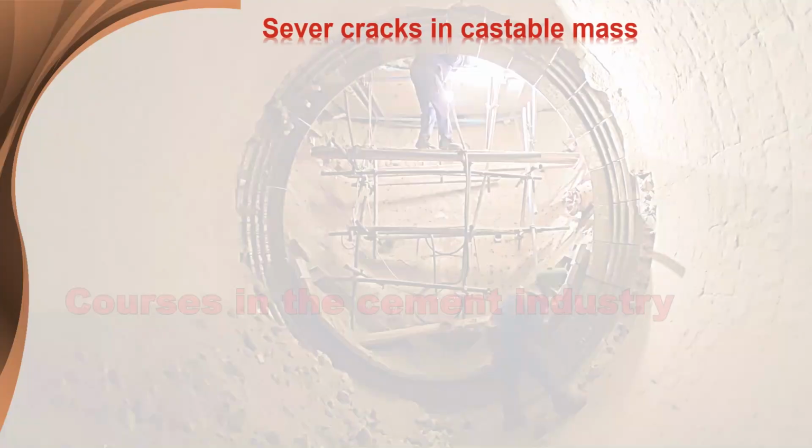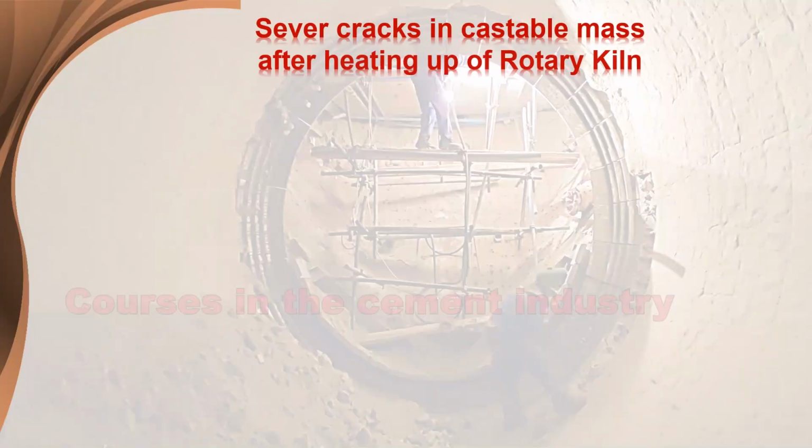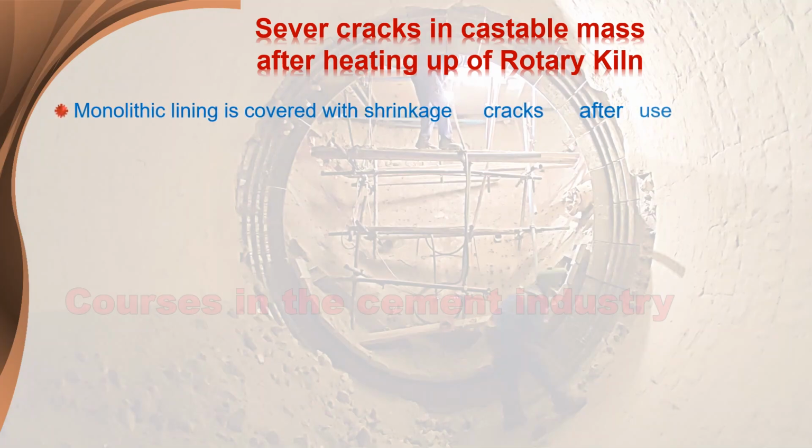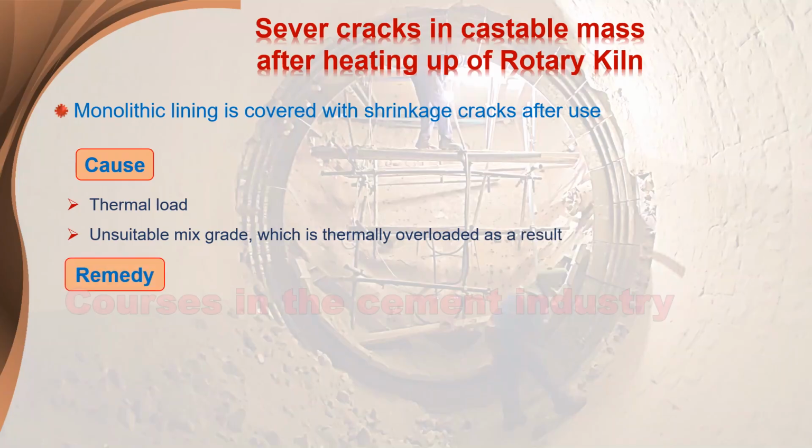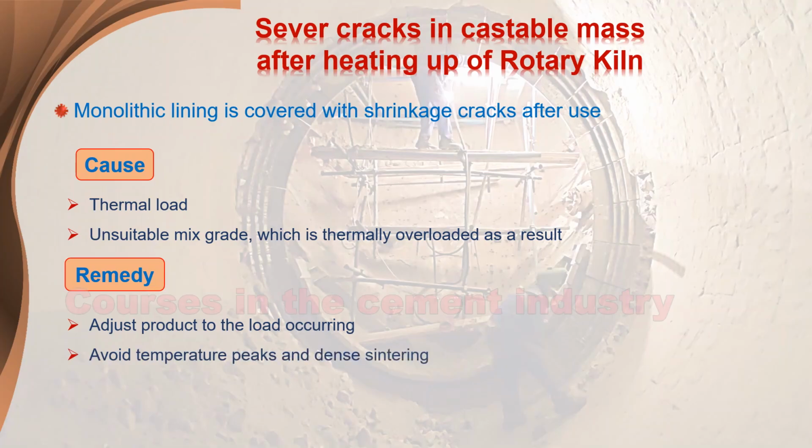Severe cracks in castable mass after heating up of rotary kiln. Monolithic lining is covered with shrinkage cracks after use. Cause: 1. Thermal load. 2. Unsuitable mix grade, which is thermally overloaded as a result. Remedy: 1. Adjust product to the load occurring. 2. Avoid temperature peaks and dense sintering.